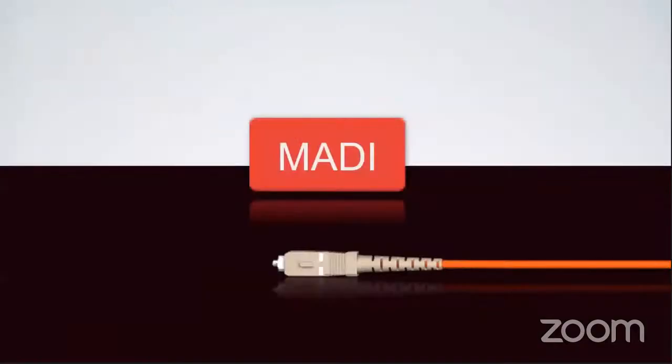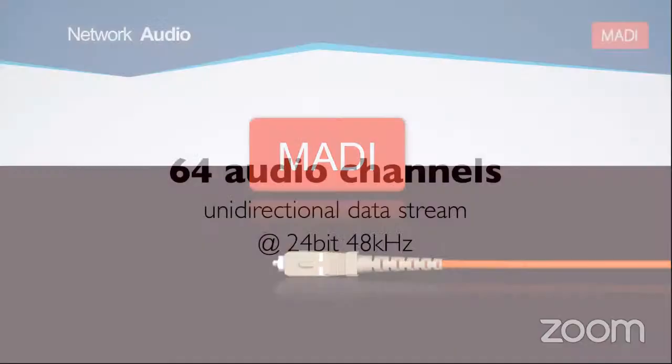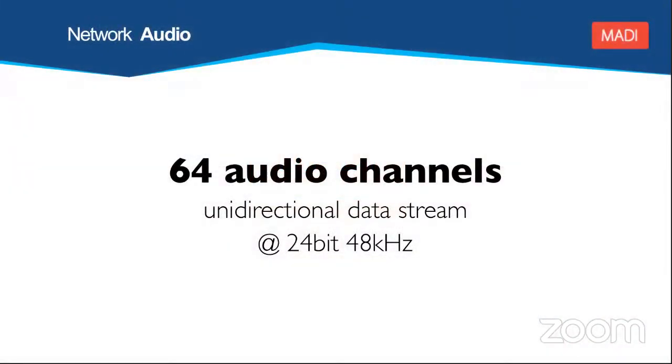So I like to talk about MADI first, which stands for multi-audio digital interface. It is a unidirectional data stream, so it works very similar to SPDIF and ADAT optical. So you have a MADI out and you have a MADI input. They're separate cables. When we talk about MADI, we're usually expressing it in 24-bit 48K, and it's 64 channels. If we go up to 96K, it becomes 32 channels. If we go up to 192K, then it becomes 16 channels. And the cable itself comes in a couple of different formats.